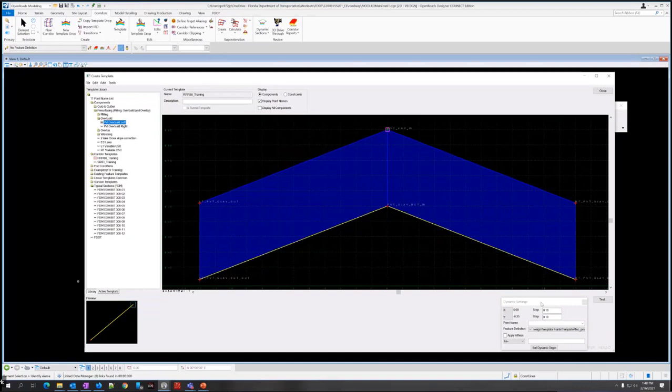All right, so I still have my dynamic settings open. So it's going to be step 9 on the page 1-18, top of that page. So now I want to check this box to apply fixes. And for step 10, we need linear templates common, outside lane with paved shoulder. So this one right here.